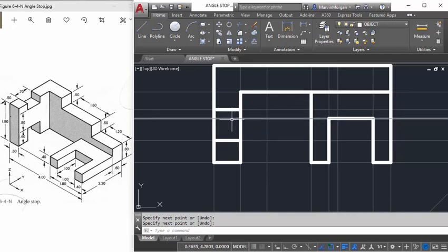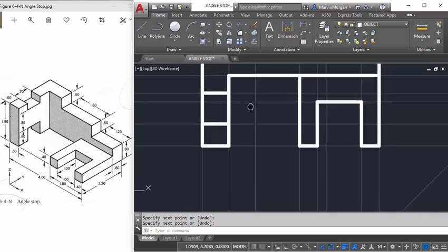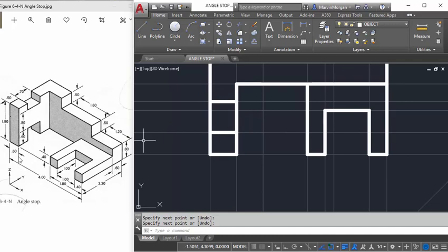And once again, the reason why I chose this line is because this line falls under that. And so therefore I know it's a possibility that there's no visible line located there. Underneath my object is directly underneath this part. So going back to the precedence of lines, the solid lines override the hidden ones. So therefore, this underneath part I cannot identify with the solid lines already there.